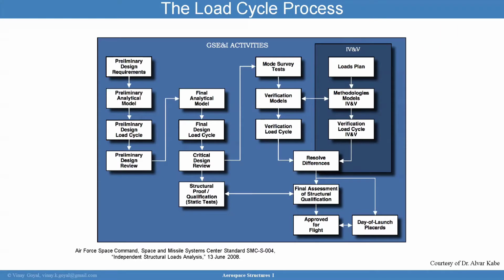they have to be performed to a load level that has been statistically defined. And those values should not exceed a particular value, and that value is established based on the customer's requirement. For space systems, the loads analyses are typically performed to obtain no less than 99% enclosure with 90% confidence.